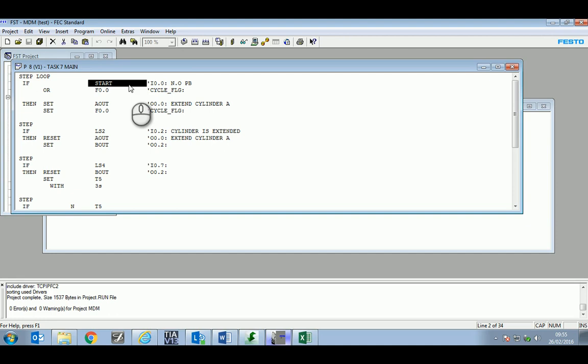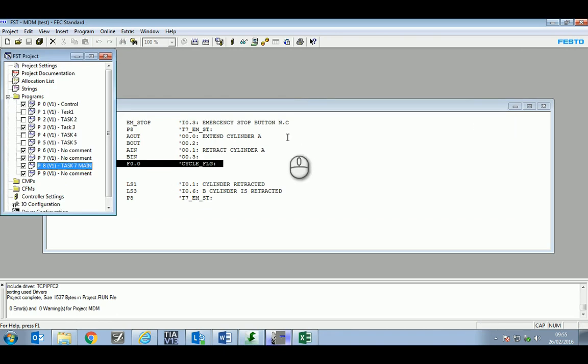Your other new method of control is now your third push button, which you're going to probably use the D10 switch for. If you press it at any point, it automatically resets the cylinders back to their initial position, and then resets the program ready for you to hit start again. Okay, so that's your two methods of control for that. If you can have a go at setting that up.